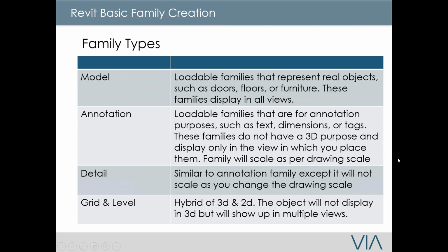Now, there are different types of families. There's model, annotation, details, and grid levels. Most often, users are familiar with the model, annotations, and details. Typically, you also have grids and levels that display a little bit differently. They're a hybrid between 2D and 3D.